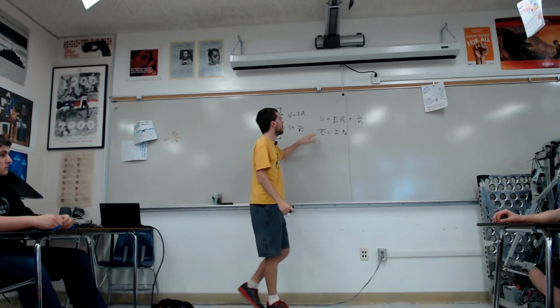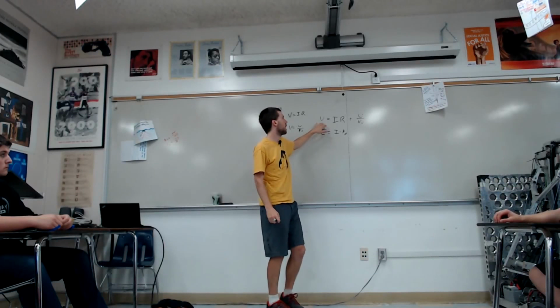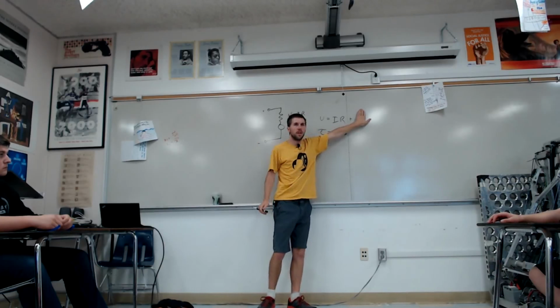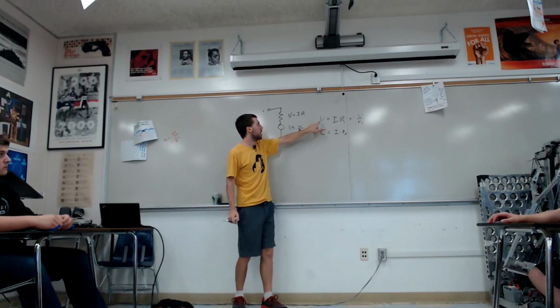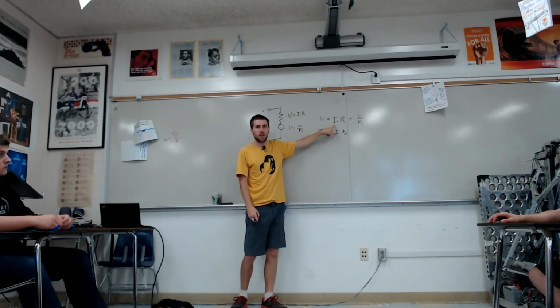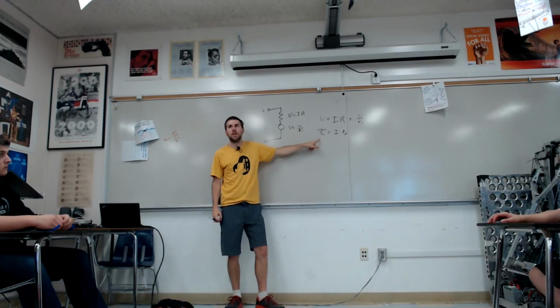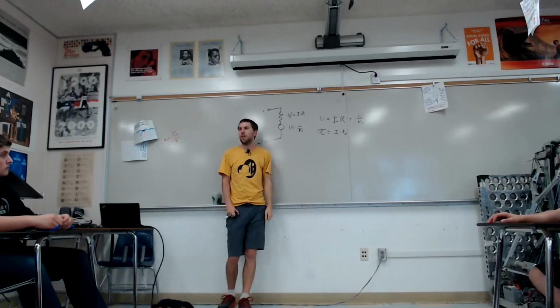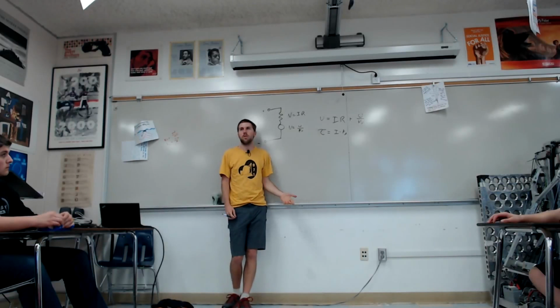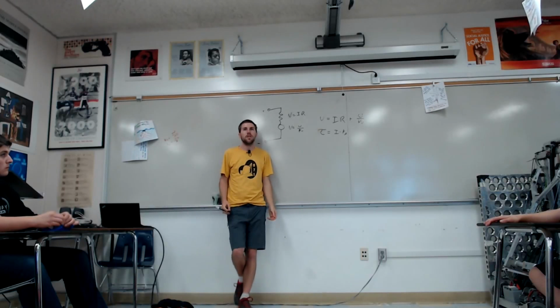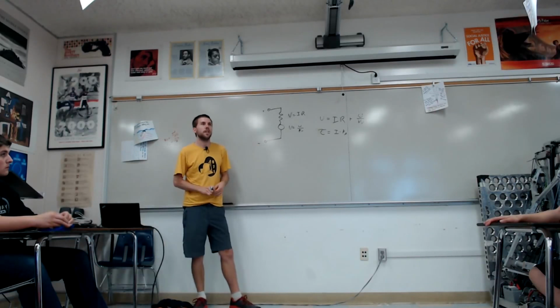Say we try and simplify this equation. Let's say our motor is stalled, so omega is 0, and our voltage then directly gives us a current, and our current gives us a torque. So if you apply half voltage to your motor, you get half torque. If you apply full voltage, you get full torque. That's something we can see in reality and go measure.